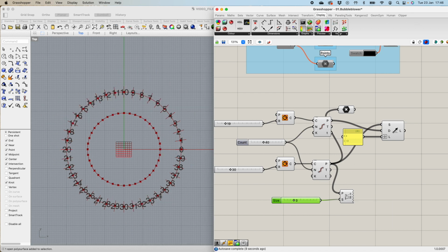You find it under vectors, right? So when I draw a circle, the circle doesn't start here. The circle has a start and an end. The circle starts in the center and then it goes from the 0 and then draws basically anti-clockwise. Yeah. So my points arrange anti-clockwise.